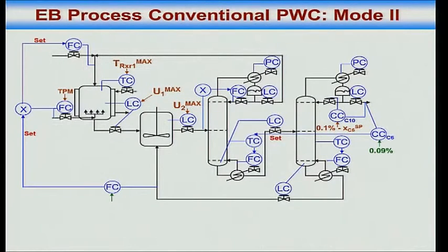So I start jacking up the ethylene. This becomes maximum. So I can't maintain ratio, that's fine. I jack up the throughput further. This becomes maximum, I can't maintain the temperature. Same problem now occurs. I can be putting more ethylene than I can boil off. I am putting more ethylene, so more ethyl benzene is getting formed, but I am limited in my capacity to boil it off. Where will that ethyl benzene go?